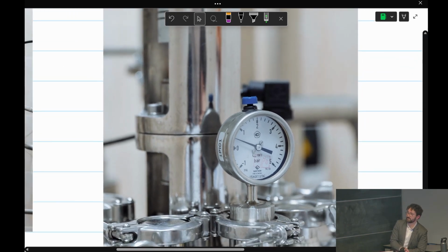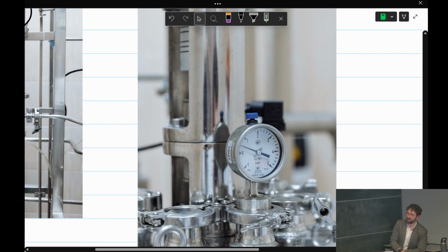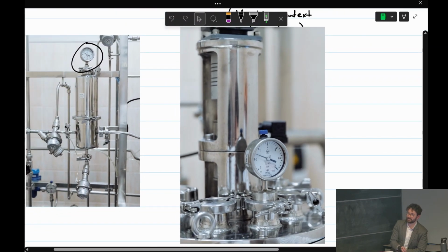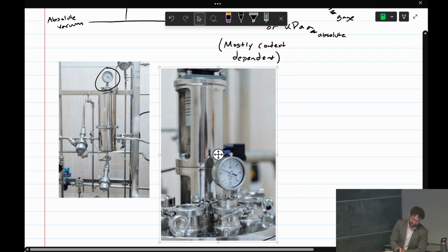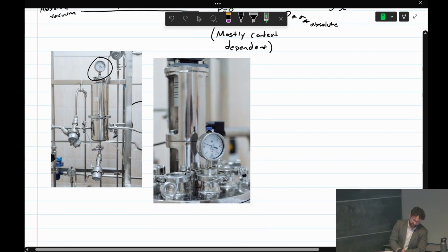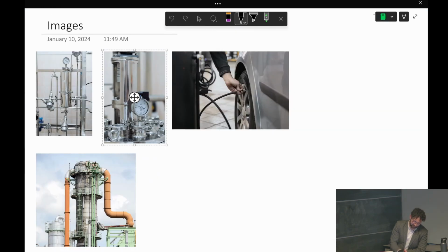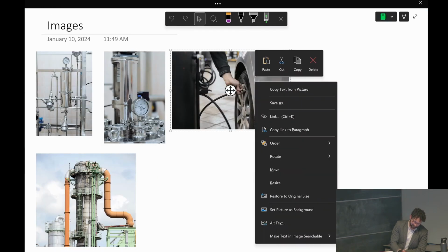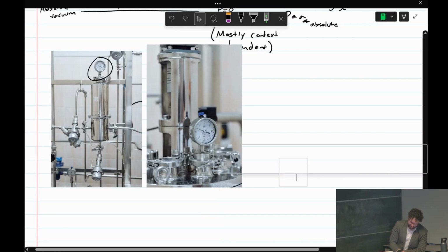And it would be very annoying to go and recalibrate all of your pressure gauges for absolute pressure, because a pressure gauge implicitly measures the difference between absolute and the pressure of whatever we're measuring. So if you wanted an absolute pressure gauge, you would need to recalibrate it every time the pressure in the room changes. And another example I mentioned was filling up the car tires. So for example, one time I had a flat tire.